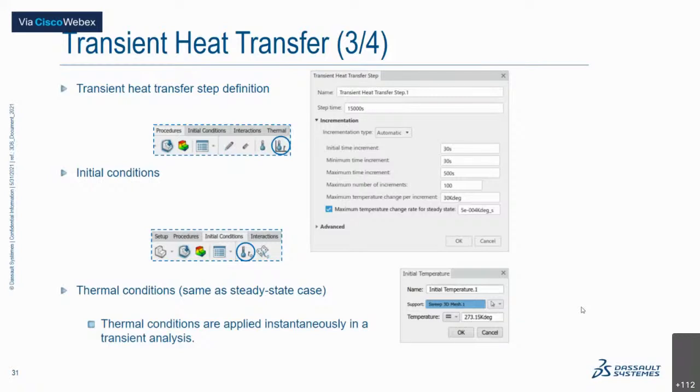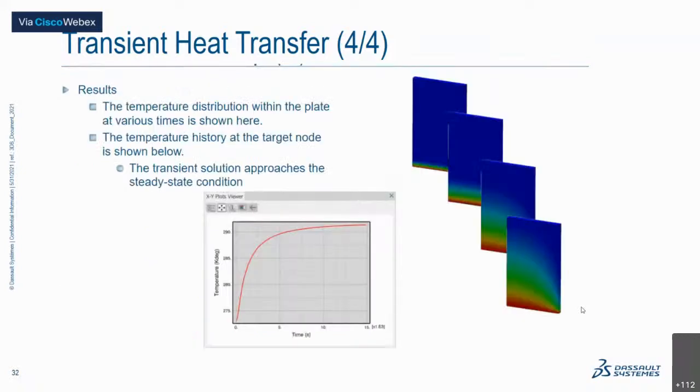And since for a transient heat transfer analysis you'll also have to define the initial temperature, you go on by defining an initial temperature value of about 273.15 Kelvin. You'll define it as an initial temperature, and then you will try to replicate the process which you did for a static heat transfer analysis, wherein at phase BC you gave a temperature value, at phase DA you gave a heat flux and a film condition, and all of that.